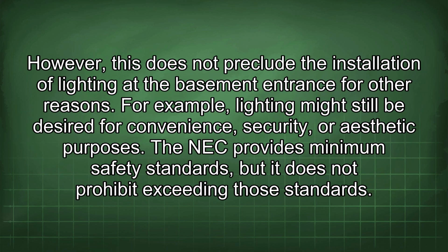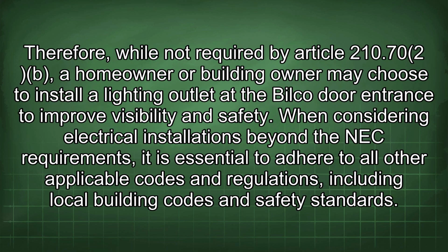However, this does not preclude the installation of lighting at the basement entrance for other reasons. For example, lighting might still be desired for convenience, security, or aesthetic purposes. The NEC provides minimum safety standards, but it does not prohibit exceeding those standards. Therefore, while not required by Article 210.70, a homeowner or building owner may choose to install a lighting outlet at the Bilco door entrance to improve visibility and safety.